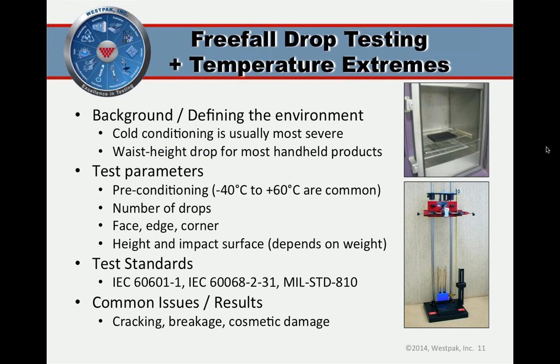Product drop testing at temperature extremes is a concept that's also been around for a long time because, as Mike mentioned, polymers, and most materials, get brittle when they're cold and tend to be a little more elastic when they're warm. And then the differences between materials rigidly attached together at temperature extremes can also add to this, especially with differential thermal expansion.